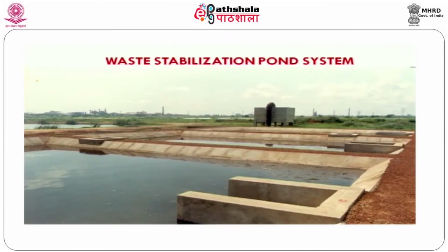That mutual symbiotic action is called algal bacterial symbiotic action. Most of the algal ponds or stabilization ponds work based on algal bacterial symbiotic actions. Two species are present there, and they are mutually benefited because of the symbiotic relationship. Algae release oxygen during photosynthetic action, which serves as an electron acceptor for aerobic bacteria. Aerobic bacteria convert organic matter present in the effluent stream into inorganic plant nutrients. These inorganic plant nutrients serve as a nutrient source for algal species.